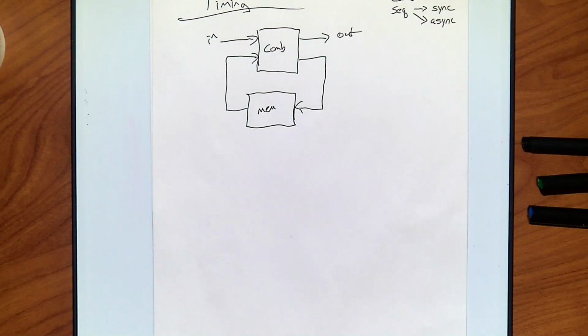What's a T? Toggle, right? Whatever it is, you get the opposite of that. You can kind of think of it as putting a negation, or technically you're doing an XOR, feeding your state back into an exclusive OR with your data coming in. If the current state is on and your data is 1, it'll flip it.